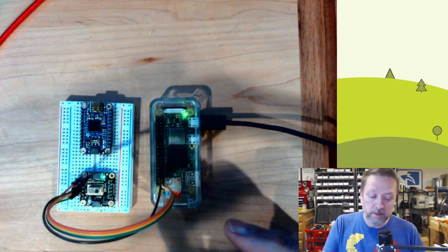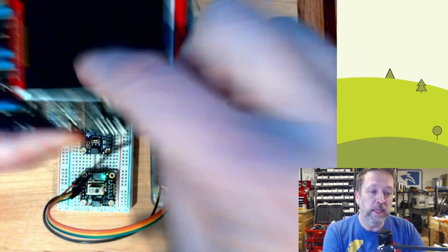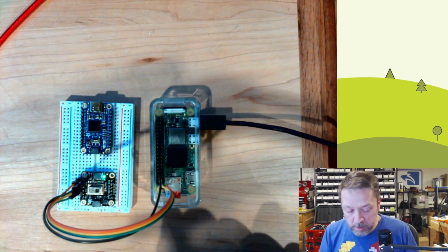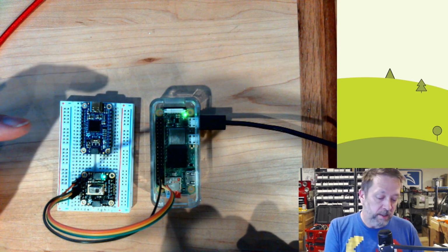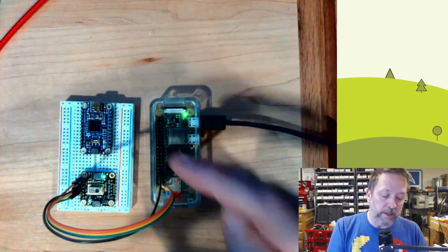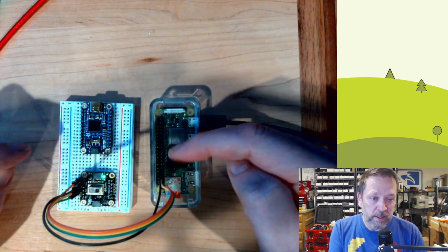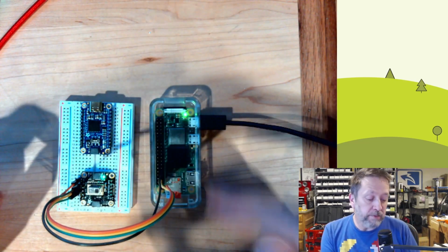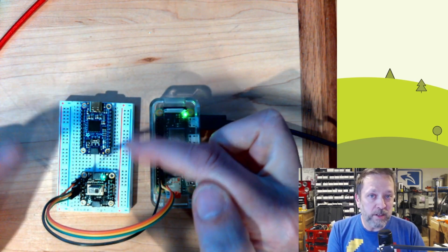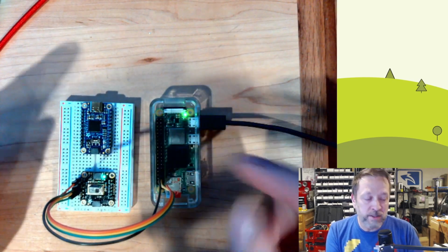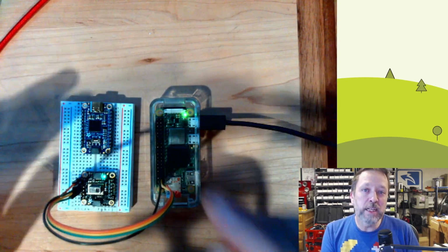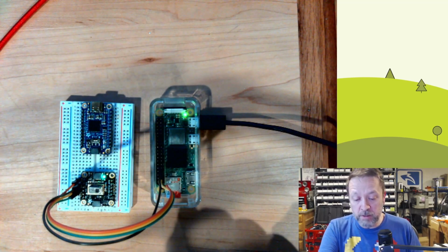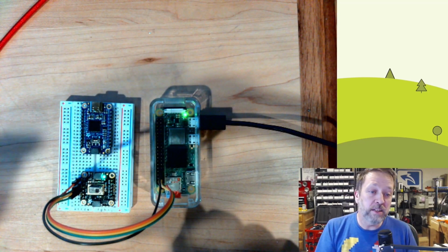My original plan was to use this display to prove that it all worked with the same hardware. The reality is that in order to run this display, it requires 9 wires off of here, and then this plugs into a breadboard, and the display plugs into the breadboard. And if you've got any experience with that, oftentimes you get a little bit of flakiness with one of these connections. At any rate, I couldn't get the display to work. The clock signal looked really ugly. And so I actually abandoned deciding to show it that way.